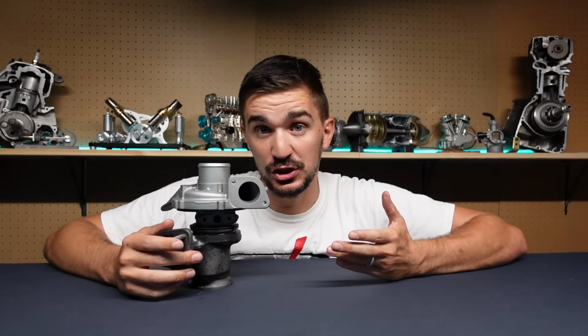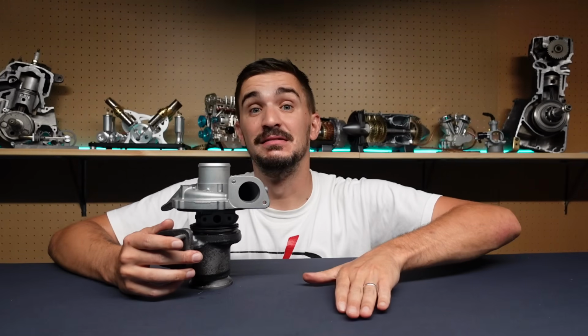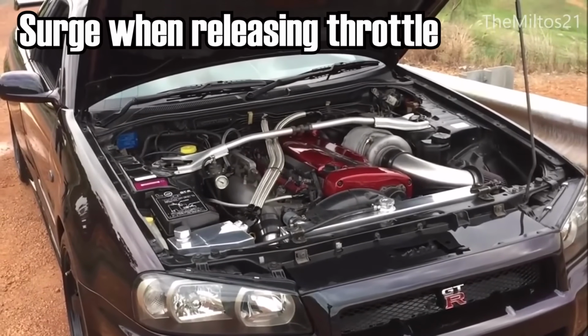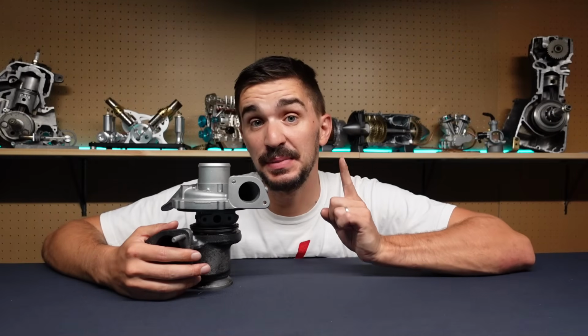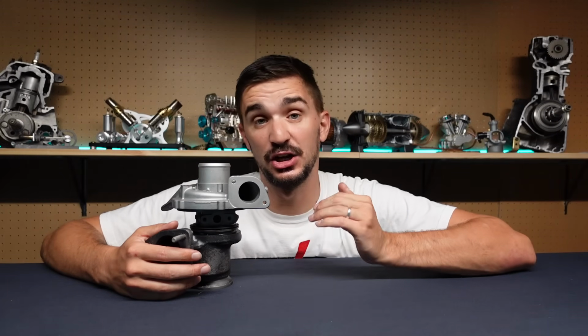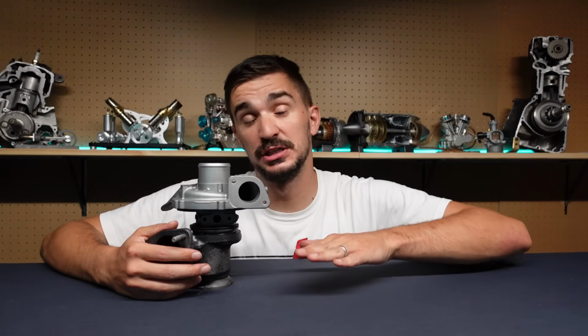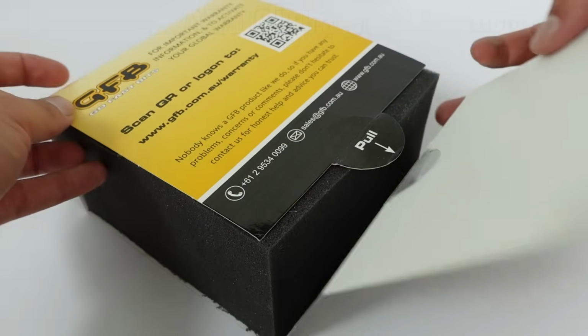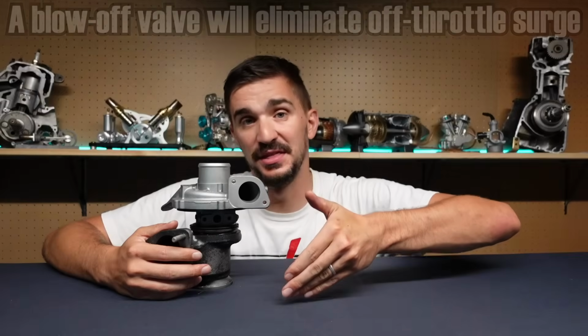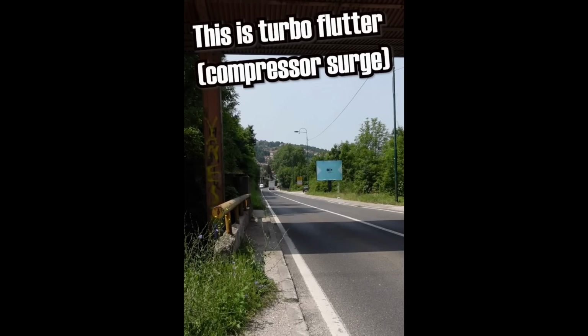The second kind of surge occurs only when the throttle pedal is released. Both of these can be destructive if they're strong enough, but surge that occurs under load is more dangerous and causes greater damage much faster. The easiest way to get rid of surge that occurs when you release the throttle is to install a blow-off valve. This converts the sound coming from the engine when you release the throttle from this to this.